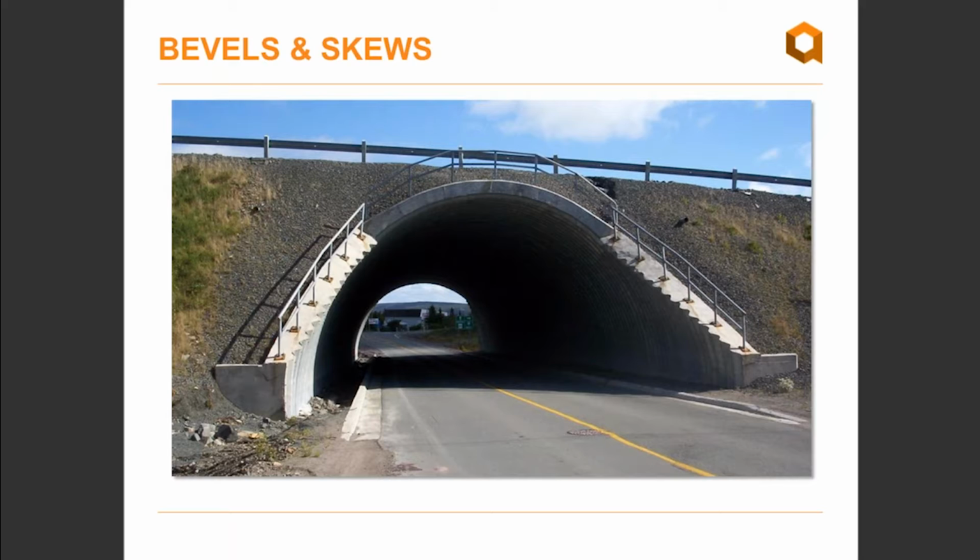One important thing to note with beveled ends, whenever a structure is cut, you need to remember we're talking about flexible systems. They rely on the soil support around the structure. So we do require concrete collar reinforcing because we're interrupting that ring compression. So usually when a structure like this is cut, the plate strength in the cut areas is just limited to the bending strength of the corrugation.